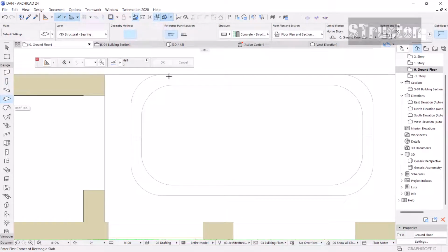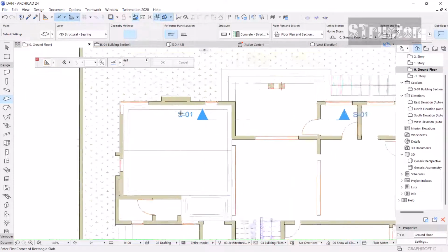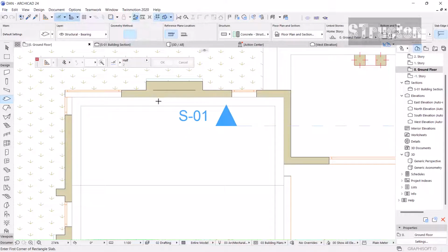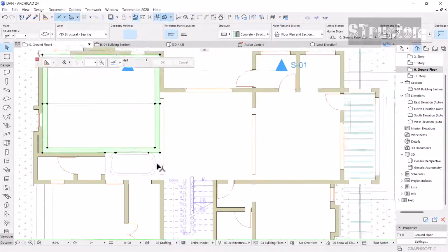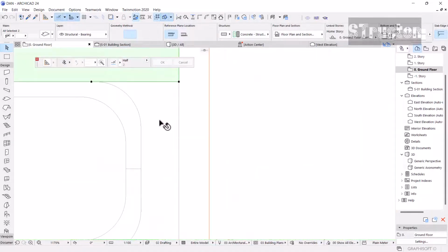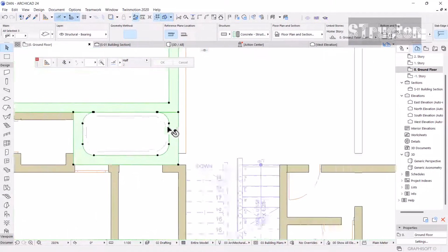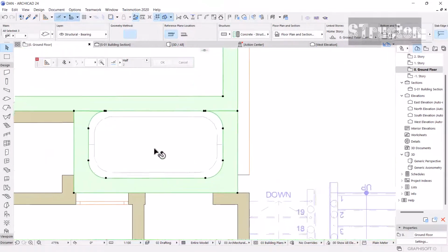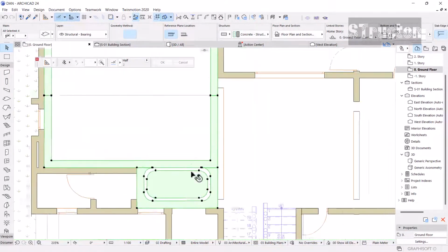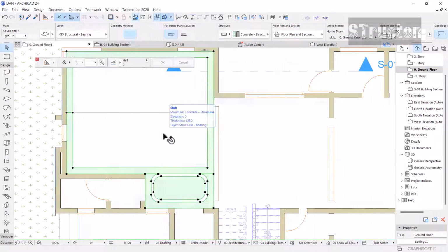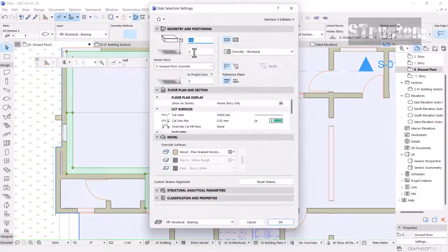Slab tool and magic wand. I can do that. Magic wand and I can do that. If we click on this and let's click on this again, because we want them to be at the same level, I'm going to select all of them, and even this one, I want them to be at the same level. So I'm selecting them and pressing Ctrl G to group them, so that when I click Ctrl T, I can now be able to adjust their position from the ground.